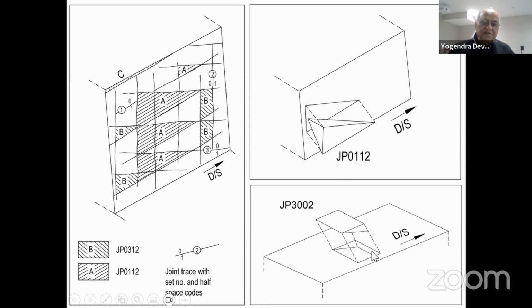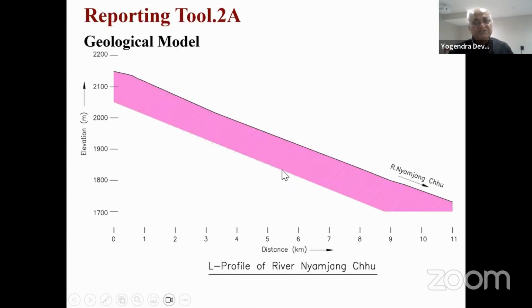This particular one is very interesting because this is in a diversion channel in a project, at a hydropower project, where these blocks are hard to decipher in the stereo plots. In your kinematic analysis, these blocks can be shown to create the covering in the bed, because under the water flow they float and come out, they loosen the other blocks and things like that. So this is one evaluation.